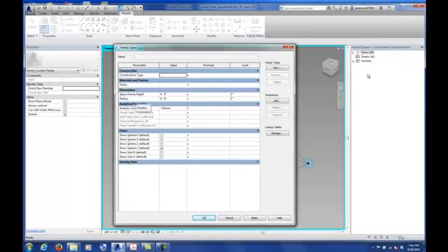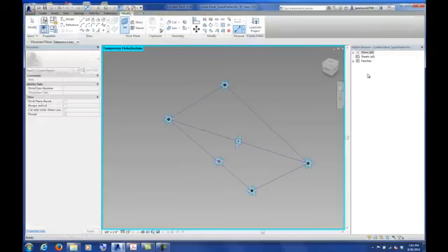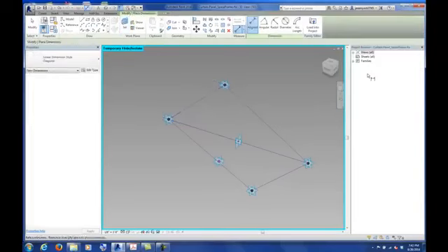Now I'm going to click on family types. When I do that, it doesn't look like it's coming out of... All right. Is that the same alignment problem? I'm going to repeat these steps one more time. Go to Align Dimension. You want to hit Set on the work plane, and you want to hover over and select one of the reference lines, not any of the points. So it hovers over, you get this little rectangle basically around your reference line. Then I'm going to select each of the points and drag off a dimension.